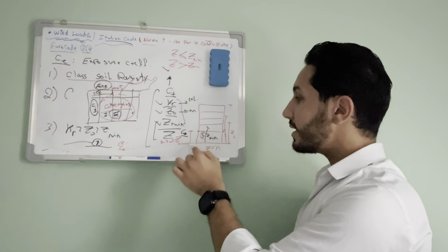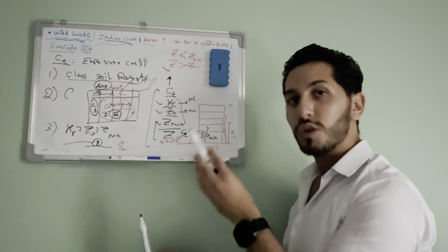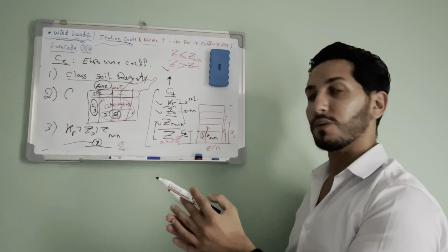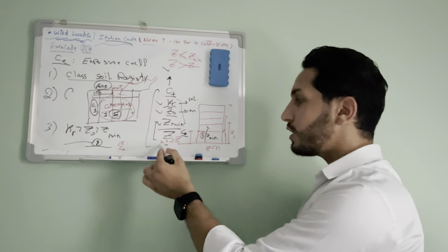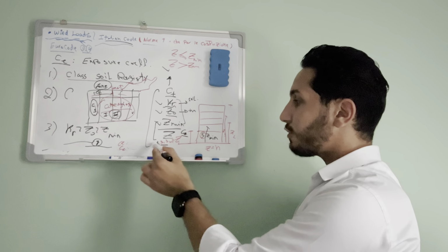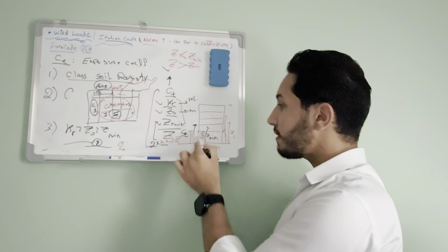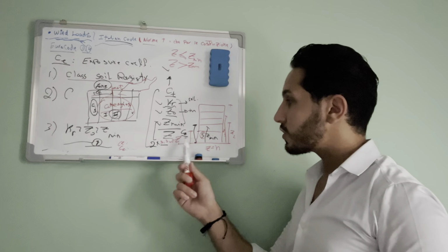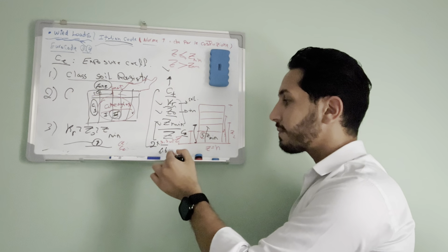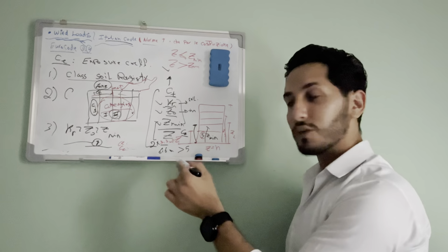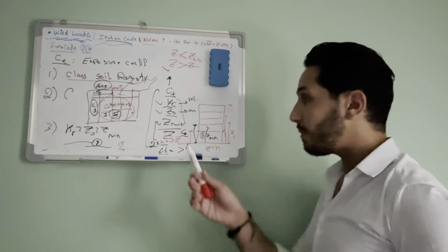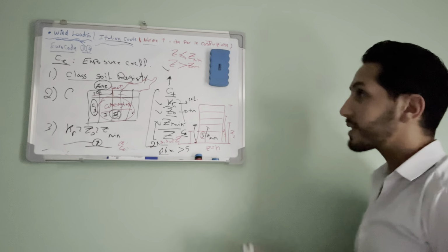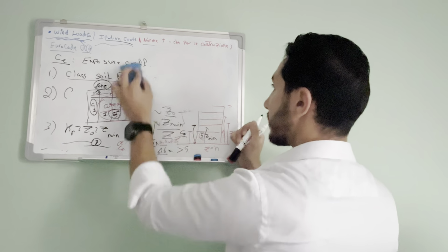What happens if the Z exceeds the Z minimum? You take the Z with the actual value as it is, which is the height of 3.3, for example. 3.3 times 2, so we are in the second floor in this part in here. So this is going to be 6.6, right? This is higher than 5, so we take this value in here. I hope it's clear for you, these calculations for the exposure coefficient.